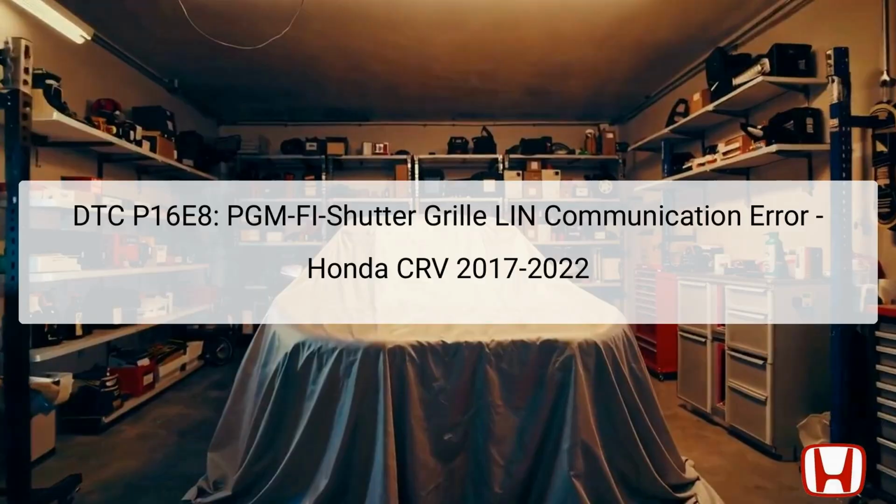This presentation addresses the diagnostic trouble code DTC P16E8, specifically related to the PGM-FI programmed fuel injection system in the Honda CRV models from 2017 to 2022. The P16E8 code indicates a communication error within the LIN, local interconnect network system associated with the shutter grille, which is a crucial component in improving vehicle aerodynamics and efficiency.